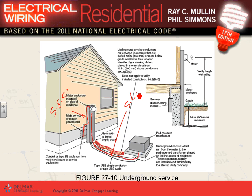There's also, you have to have a warning tape, guys, for your service lateral. The code requires you to put a warning tape. So you bury your conductors at 18 inches. So here's my conductors. From here to here is 18 inches, not 18 feet, that would be a lot. And then you put a tape right at the top of it, guys, from here to here, 12 inches. So a foot.